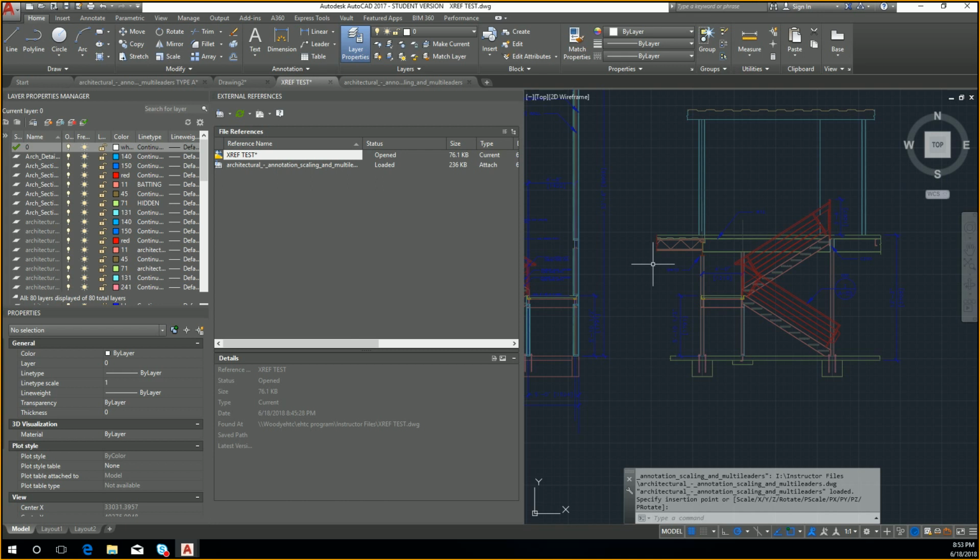It's in your drawing. So the other thing you can also do, if you were to delete the block, it would still be in your block list. So you haven't exploded anything, but then you can actually still purge it. Because if it's not living in your model space, as in it's not physically there, then you can purge it. Now if you click close, you type I.